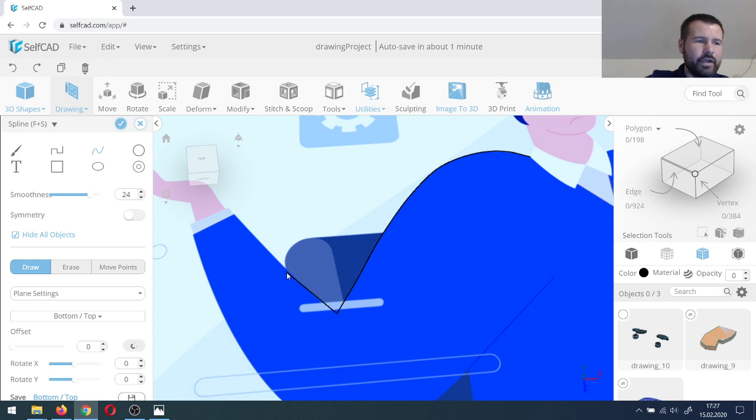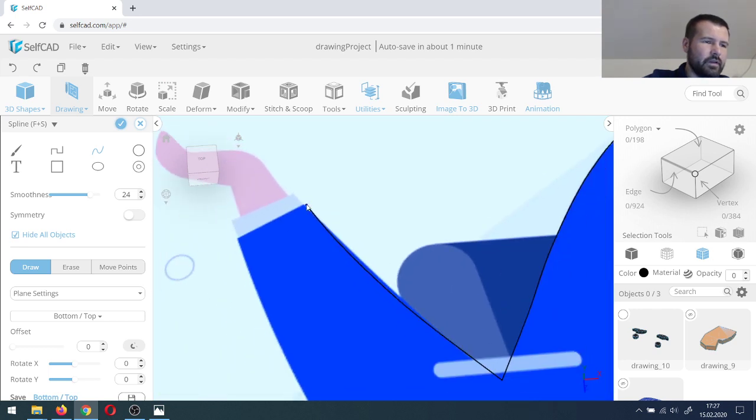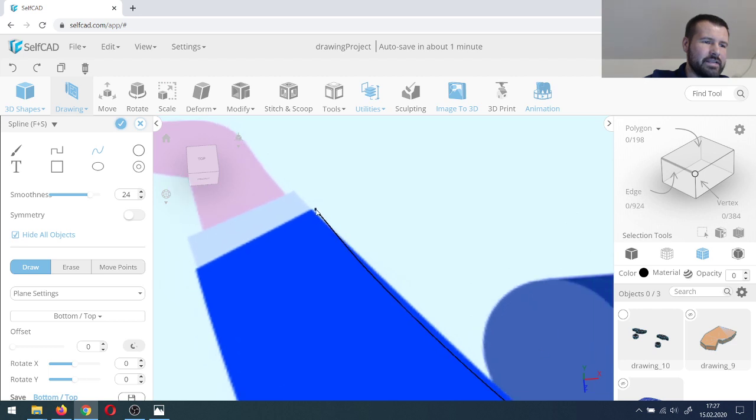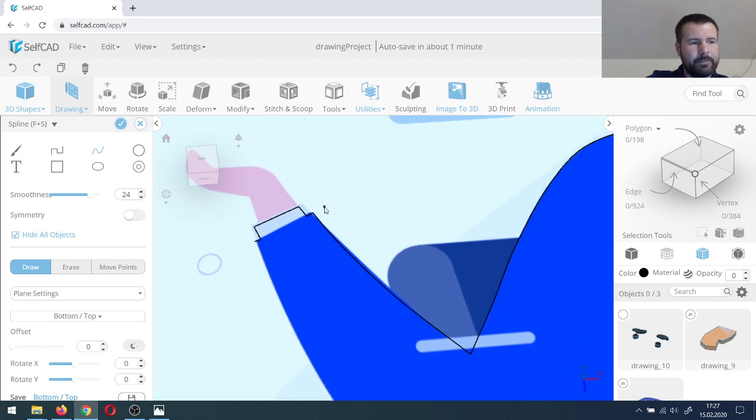draw lines. So without changing the mode of drawing right now, if I double click on the last point and then I use snapping once again, I can triple click to achieve a straight line between those 2 points. Here I need to basically do the same without going to the line mode. So basically triple click and you can move on with the next drawing like that.